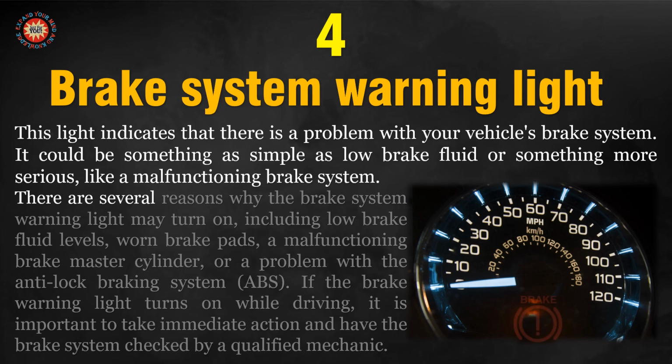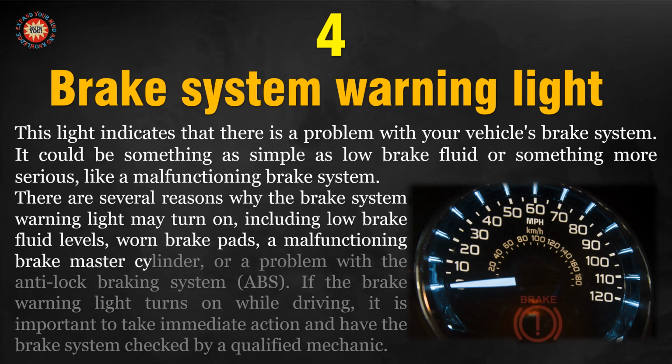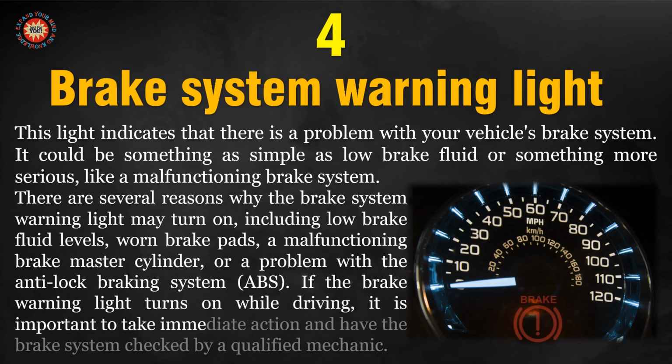There are several reasons why the brake system warning light may turn on, including low brake fluid levels, worn brake pads, a malfunctioning brake master cylinder, or a problem with the anti-lock braking system, ABS. If the brake warning light turns on while driving, it is important to take immediate action and have the brake system checked by a qualified mechanic.